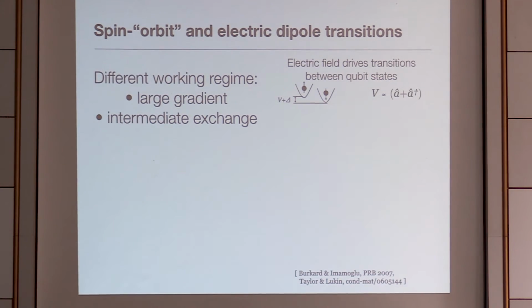We're not going to use intrinsic spin-orbit coupling, though, because I want to do it in silicon, and silicon doesn't really have intrinsic spin-orbit. It's very weak. So we're going to have to add our own spin-orbit. So you go to the spin-orbit store, and you start poking around to see how you can make your own spin-orbit. Of course, you can do it with strain in the form of Rashba. Or you can do it by adding magnetic field gradients in particular. Because spin-orbit coupling is an orbital difference in the spin, which can arise if there is a spatial dependence in the magnetic field.